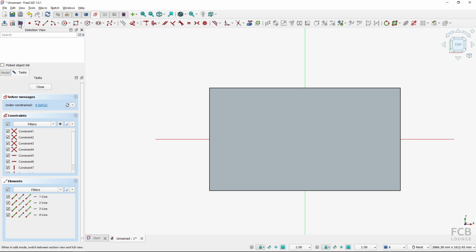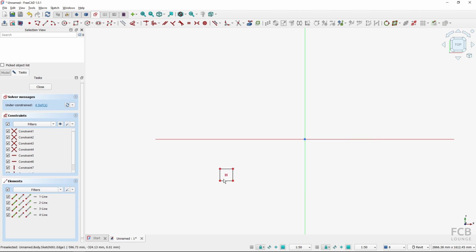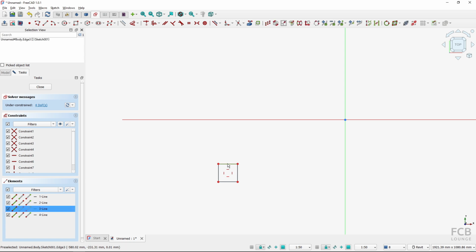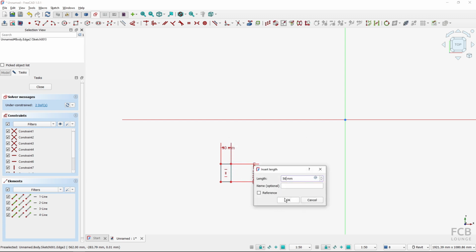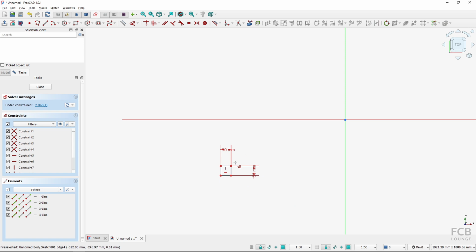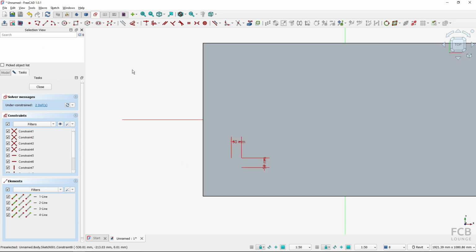And actually I will first hide it, and I want to constrain this length, so I will click like so, and it will be 50 millimeters, and I want to constrain this length, and I want to have the legs 50 by 50 millimeters. If I hit escape, now I can drag the position anywhere I want, so I want to constrain this, and I want to constrain this relative to the tabletop size. So what I have to do is show the tabletop, and I cannot use the dimensions from the geometry that is not inside of the sketch.